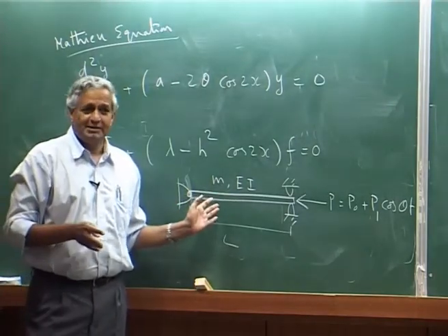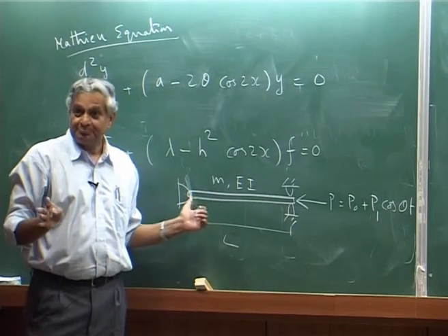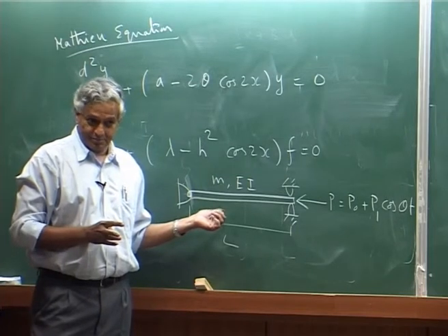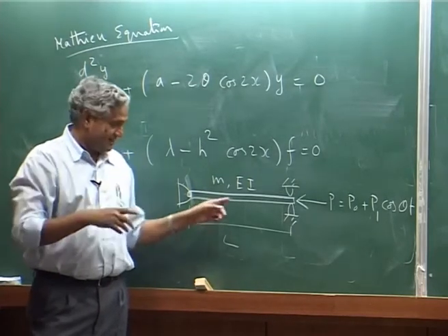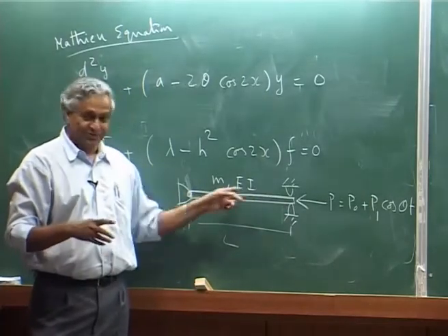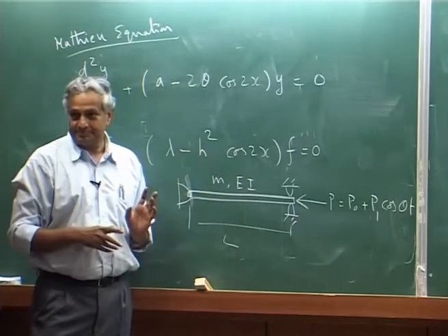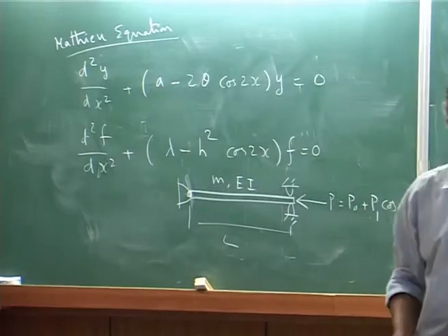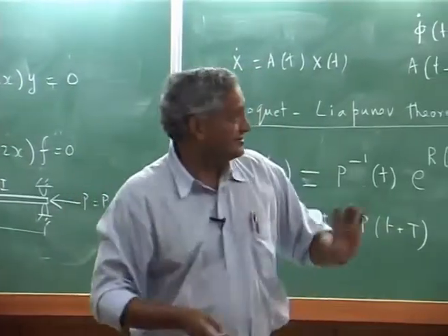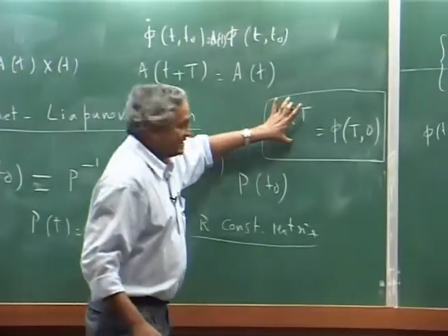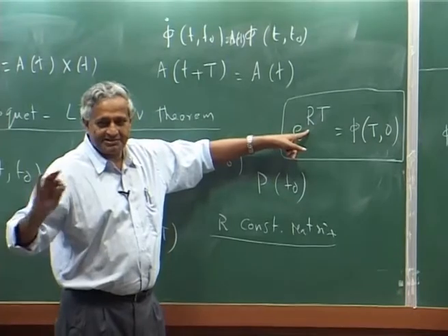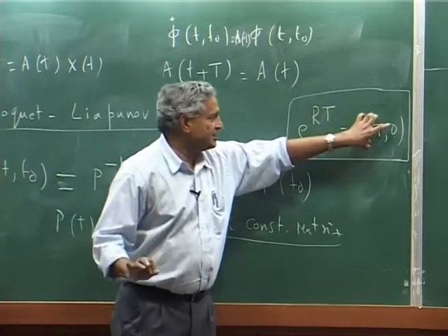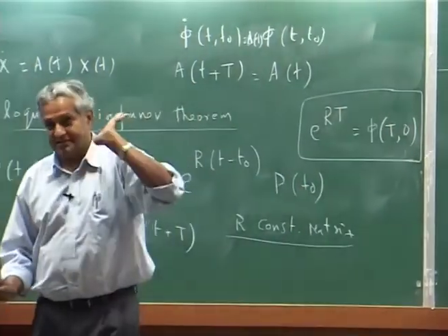Suppose I give you this problem, go and derive the equation. This is an axially loaded beam. If you want to derive, this is of course much easier, because I am putting the same axial load throughout. I can vary the axial load. This you study if you take theory of vibration next time. The procedure is to get the transition matrix and relate the eigenvalue. I am not going into the details because it is a little advanced, and the stability of the system is purely based on the eigenvalue of this transition matrix.